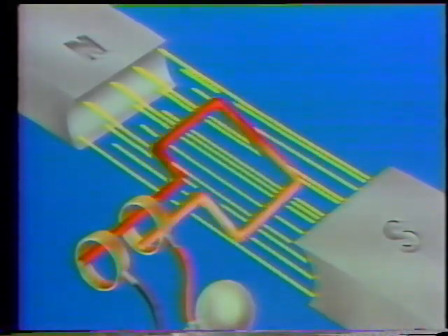From here, 0 degrees, to here, 180 degrees, this part of the conductor is cutting downward across the lines of flux, while this part of the conductor is cutting upward. From here, 180 degrees, back to here, 0 degrees, the motion is reversed. The part of the conductor that was cutting downward across the lines of flux is now moving upward, and the part that was moving upward is now cutting downward.